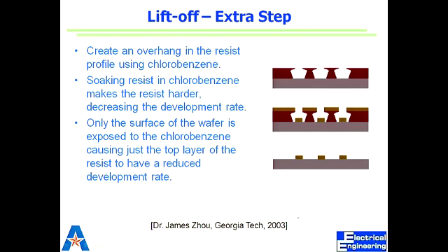So in any case, the bottom line is I can define the same lines using lithography and etching, right? Or I can define the same lines by doing lift off. For lift off, all I need is a solvent that can dissolve photoresist, right? Acetone can do that. But if I want to do etching of metal, it requires much more expensive and dangerous chemicals. We can do etching with reactive ion etching as well, but then again, the recipe requires much more dangerous and expensive processes to do that. Right?